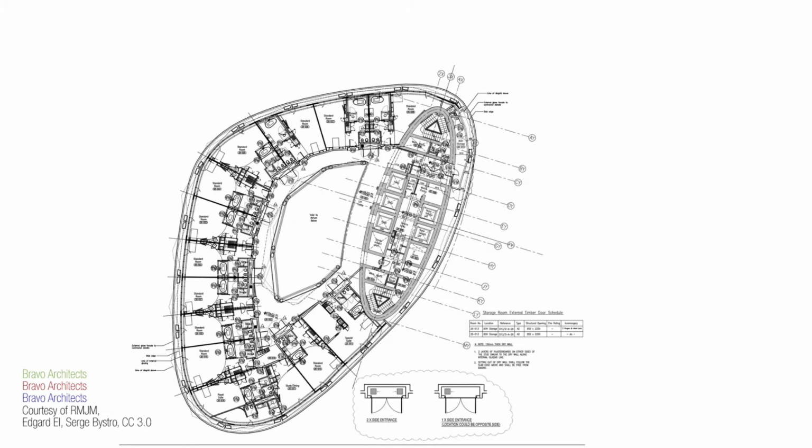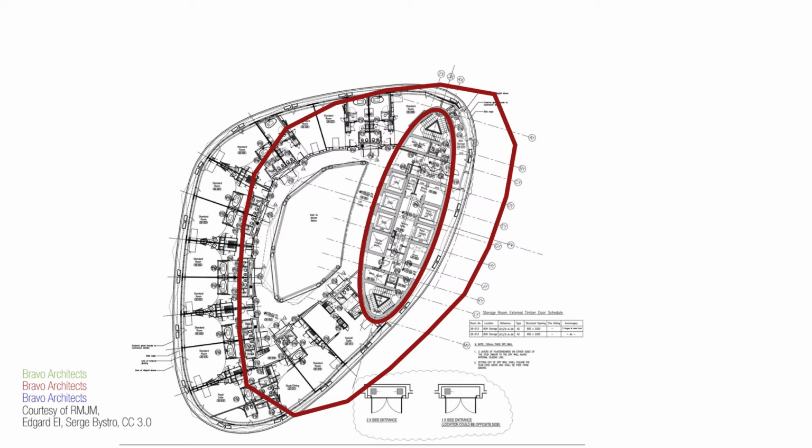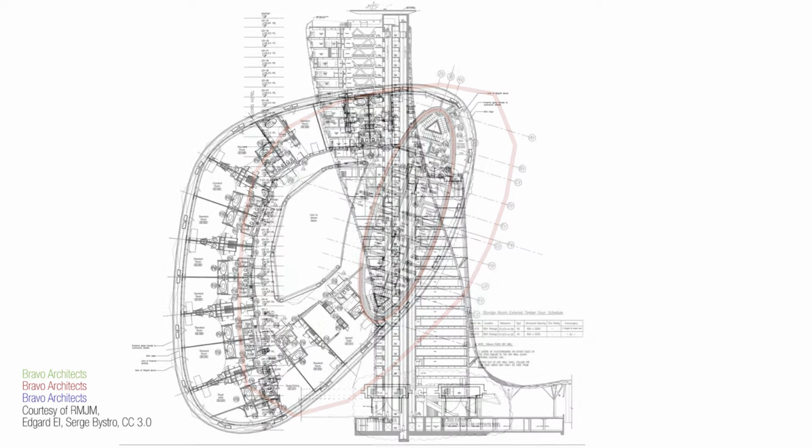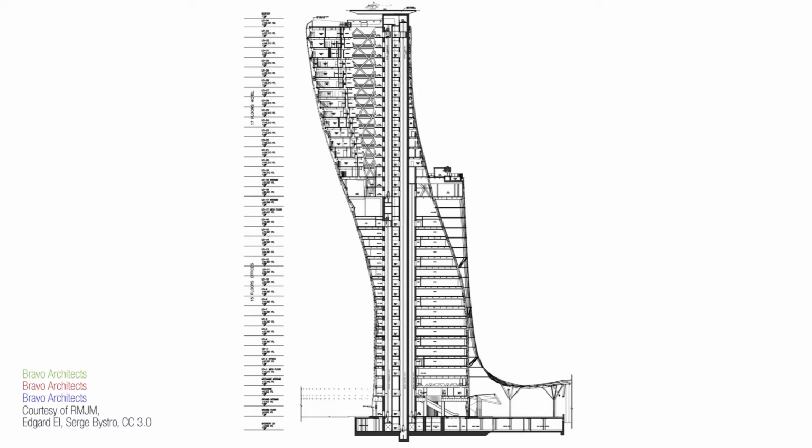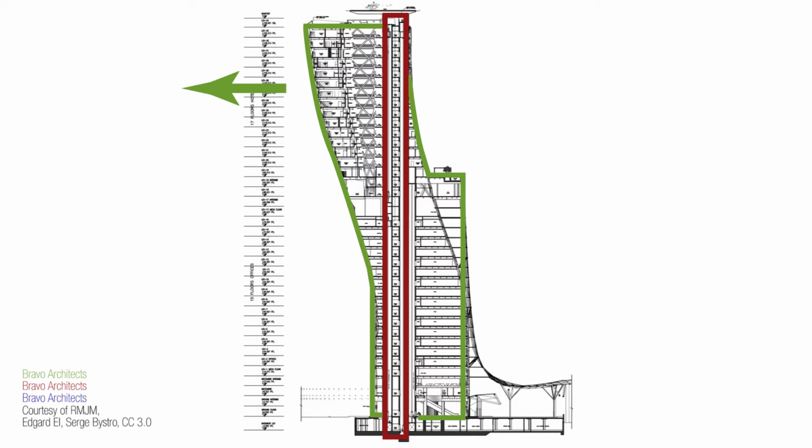While the area on the right side of the core on the 26th level plan is almost zero. And this is the projection of the 20th level plan on this level. When we look at the section, we can see that the core is climbing up in a straight direction while the floors are altering as they get higher and higher. You see the floors on top are trying to push the center of gravity really hard to the left side.